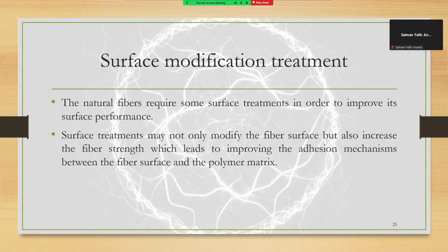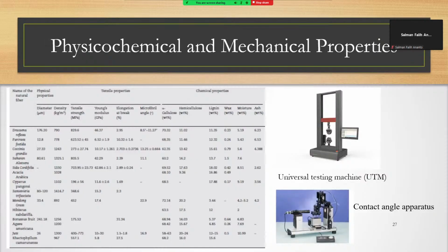In practice, the diameter of natural fibers is measured using a digital micrometer or a microscope, either an optical microscope (OM) or a scanning electron microscope (SEM). The digital micrometer permits measurements within an accuracy of 0.001 mm. Otherwise, measurement by an air wedge, with plus or minus 0.001 mm, is another alternative technique. And the density of the fibers can be measured by a pycnometer.